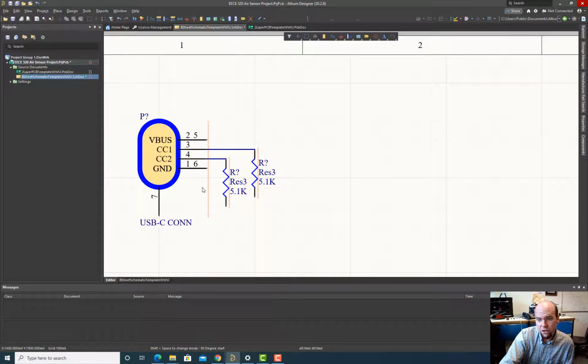So one thing we could do is run these wires over here, run another wire, and then drag this ground everywhere. But it's easier just to label the ground and say, this ground is a signal called ground. Anywhere we place that signal is going to be our ground. So I'm going to click this ground power port here, and place it here, here, and here, then hit escape to cancel.